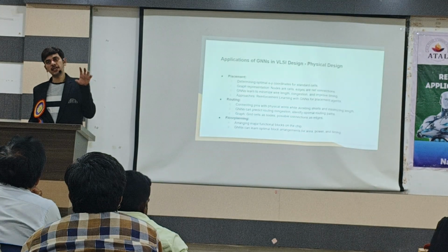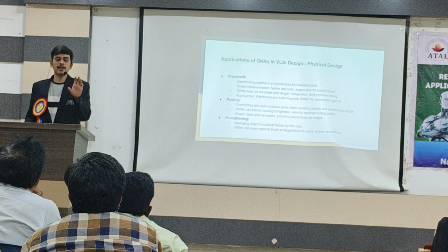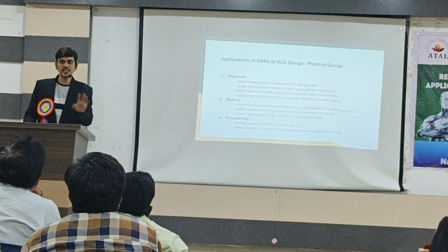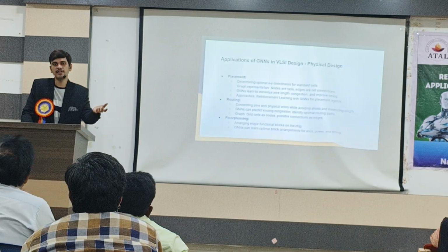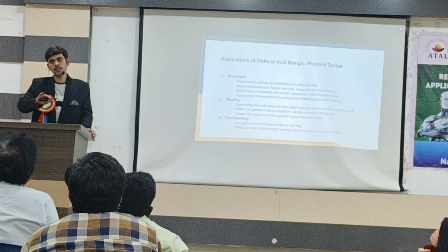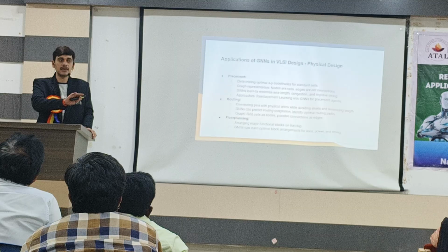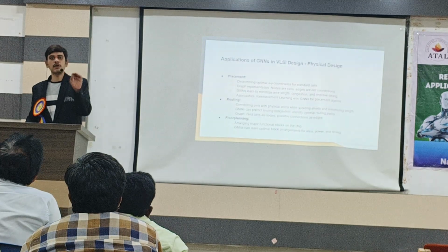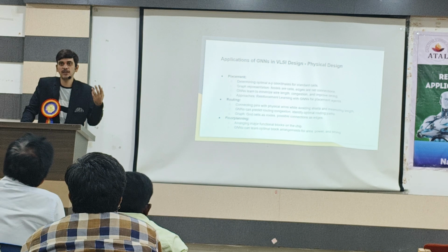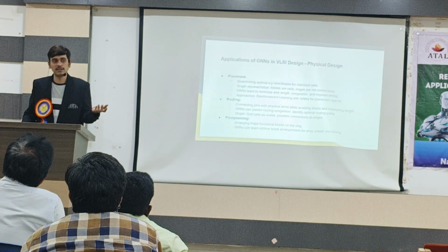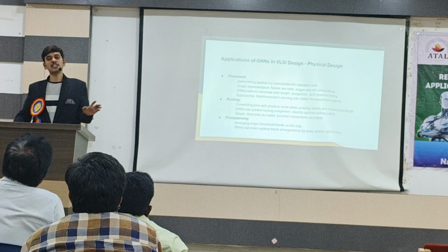So in the industry, what we do in the synthesis stage, we mostly check the setup, whether it is proper or not, with the constraints initially. Once the constraints are clean, only then can we go ahead with the design. So in the initial stage of the project, we do the constraints cleanup, and in synthesis we check the setup and check the hold, whether it is okay or not. For example, if we receive a 1000 ns violation, actually it's a fake violation, because that much huge violations won't come. That's because of the constraint actually.